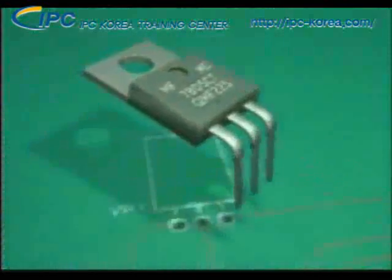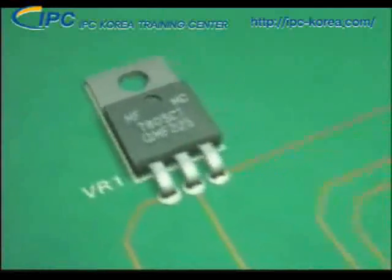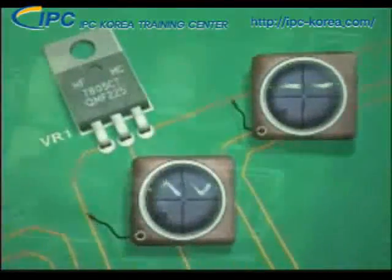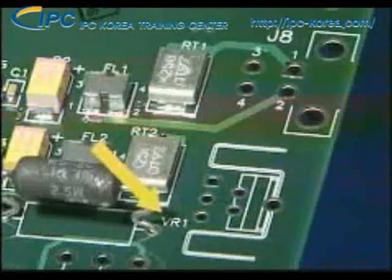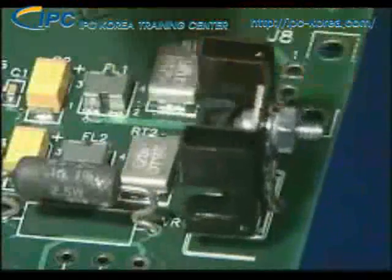Now let's examine voltage regulators. Voltage regulators keep voltage constant in a circuit by minimizing peaks and valleys. The reference designator is VR, and there is usually an angle on the body or an indented dot for orientation.